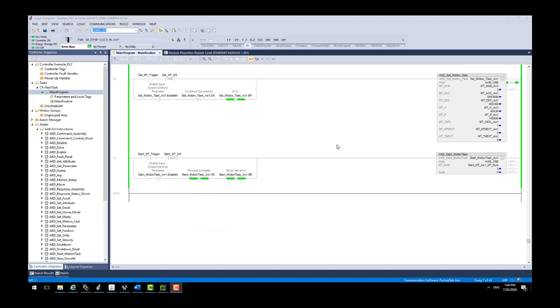I'm going to make one final minor change here. I'm going to set the MTCNTL control word for this set motion task to 0, so that we're going to continue with the example application of extend and retract, or go out and return motion task working in absolute mode.